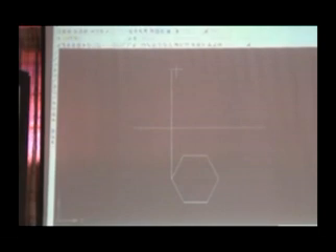Directly by command you know it. Then suppose I want to draw the projection of this. How will you construct? You will draw the projector lines. Extend the projector lines. So again, which command can I go for? Line command. So just the line command I can draw it. From here I can go for a projector line. So what height you want? You can draw it.